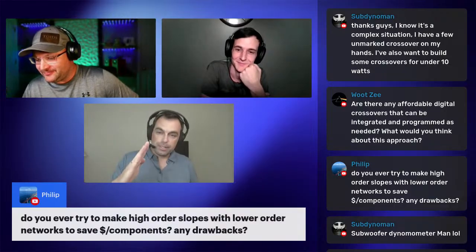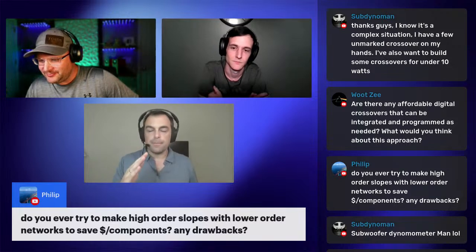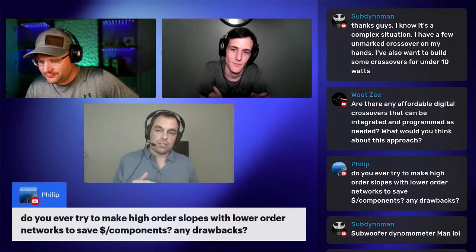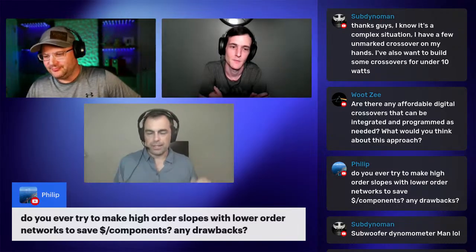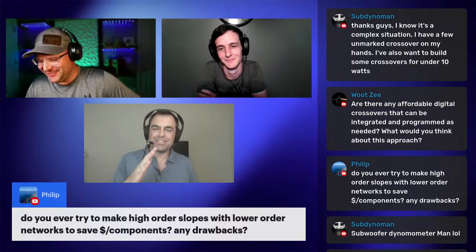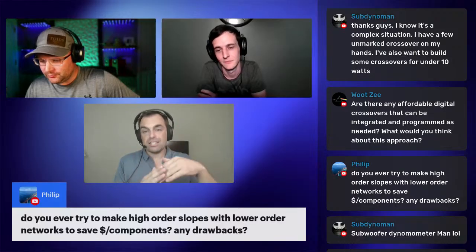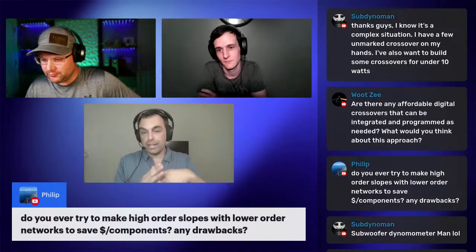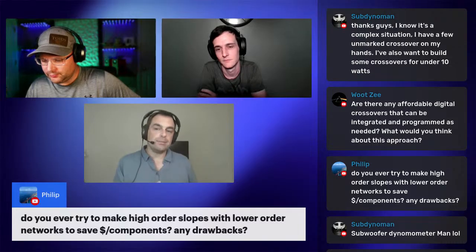So yeah, back to the thing. We've got this 12 dB per octave roll off on our tweeter, around 1500 hertz, let's say. Now, if we add a capacitor to this tweeter, we're going to assume impedance is perfectly flat and there's no hanky-panky going on. We add a capacitor that puts an extra 6 dB per octave transfer function on the frequency response. So now that tweeter is rolling off at 18 dB per octave.